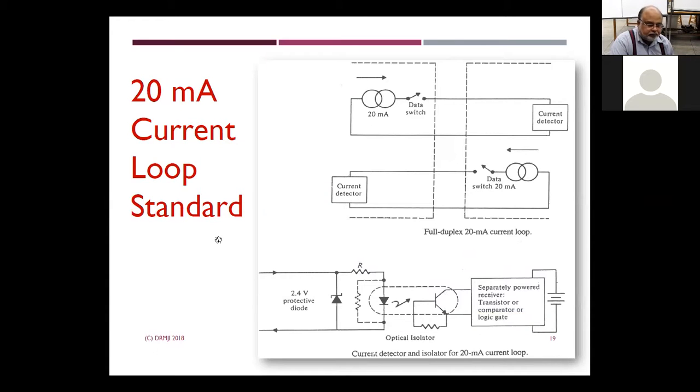Many motor drivers you buy, they specify that the digital inputs or PWM inputs that control this transistor have optical isolation. Inside you could have a PWM signal. This side you could have this transistor, but optically coupled. So the motor side, which is the high voltage side, has no electrical connection to this. Very important.